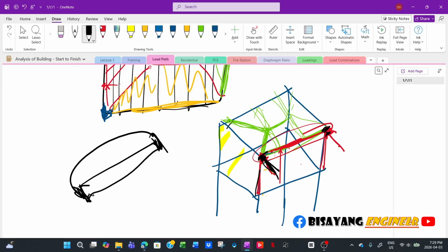So that's really important. It's crucial that you apply the loads properly. Like I said, if you're framing, if you have some kind of metal stud, then it will transfer through the beam. But if you don't have a roof diaphragm, then it will act as a horizontal load to your beam, and then it will be transferred to this frame here.